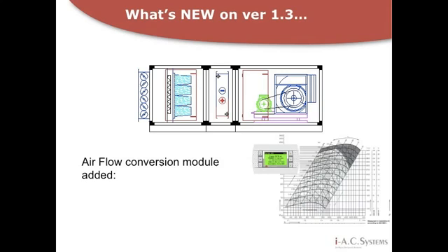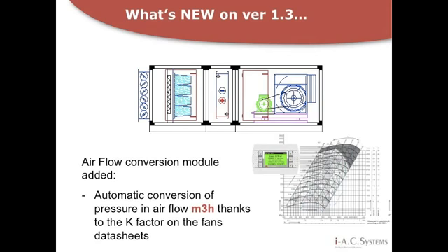A nice new little feature is the fan conversion flow rate module. By applying the conversion factor found on every datasheet of the fans, the software will automatically convert the pressure into airflow in cubic meters per hour. All set points will also be converted into this unit of measurement.